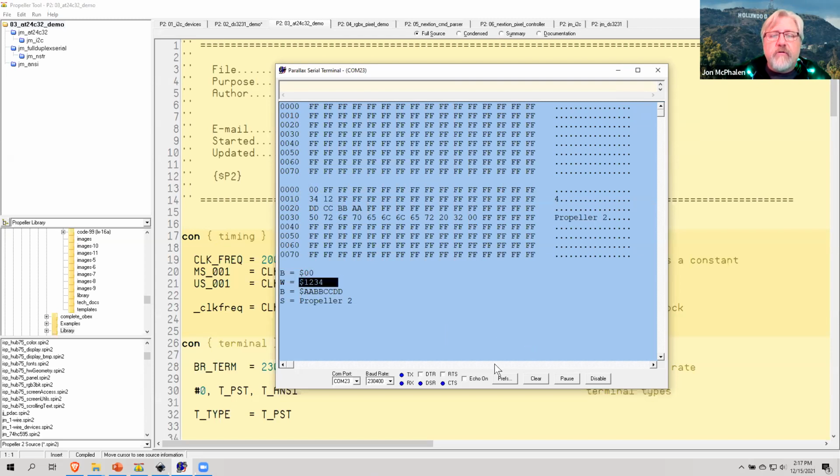So here the value is hex 1234, but you notice that the low byte comes first here. So this is showing us little endian. Same with the long. Notice how the bytes are reversed from what it appears, but that's because this is the low byte and this is the low address. You can see that. And then the string does go in order.